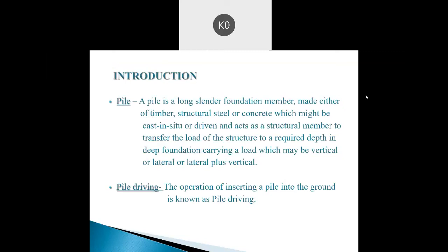Introduction. A pile is a long, slender foundation member made either of timber, structural steel, or concrete, which might be cast in situ or driven, and acts as a structural member to transfer the load of the structure to a required depth in the foundation, carrying a load which may be vertical or lateral plus vertical. Pile driving: the operation of inserting a pile into the ground is known as pile driving.